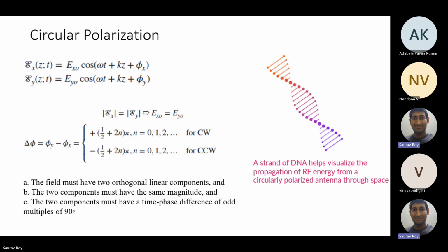But here you see the counterclockwise and clockwise have been defined in terms of plus and minus. I will advise you not to go blindly by some equation, because they must have taken a reference z direction and all this that you don't see. So you have to have your own approach. If you are given some wave, first try to draw the polarization ellipse yourself.